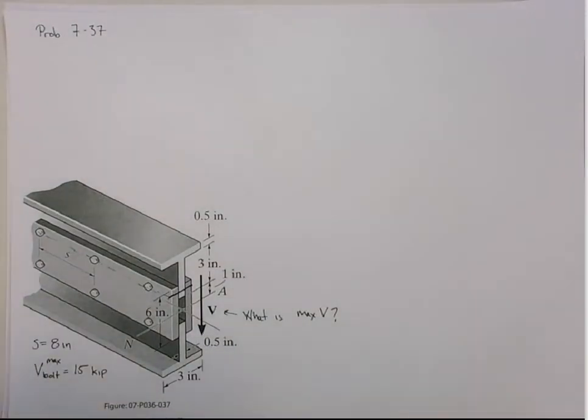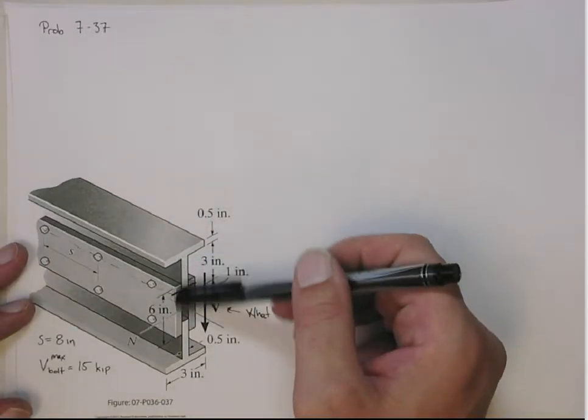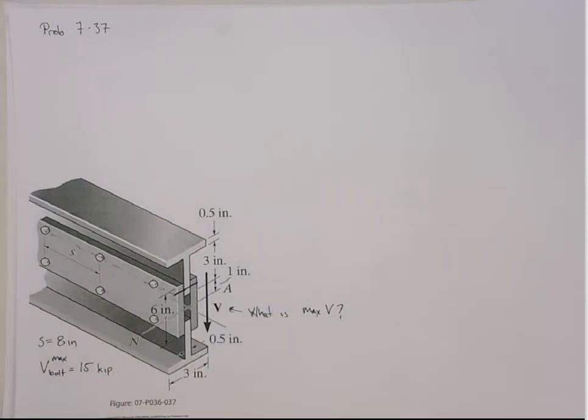If you look at this top section, I guess these are always a little trickier to visualize. Or maybe it always seems a little less believable that we actually use the transverse shear flow from the VQ on I to get the force in the bolts when the bolts are on a plane that's perpendicular to this actual shearing plane, okay?